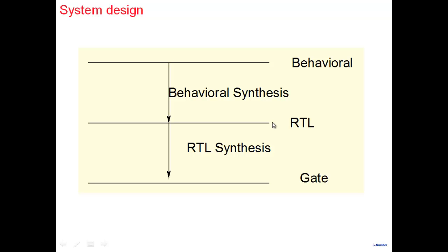So remember earlier I was saying that whatever is the description of the problem, you map it onto a state transition graph, and then you design your finite state machine. Now I'm saying whatever is the description of your system, you map it onto a data path controller kind of architecture. And then once you have that, if you recall, the elements of data path and controller are adders, subtractors, registers, and things like that.